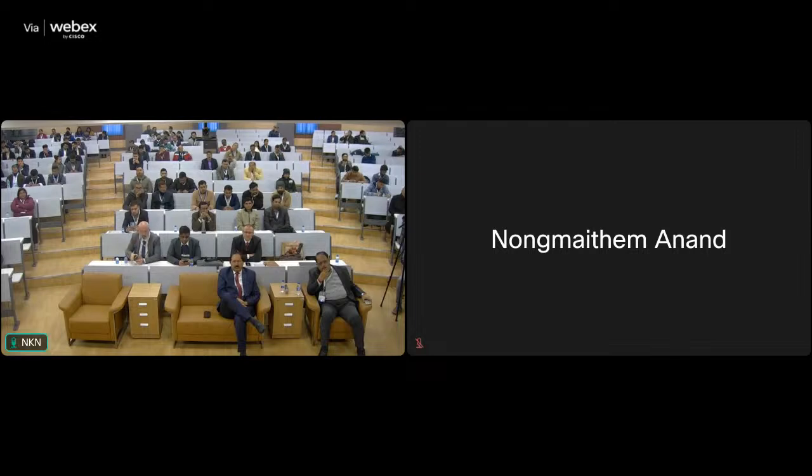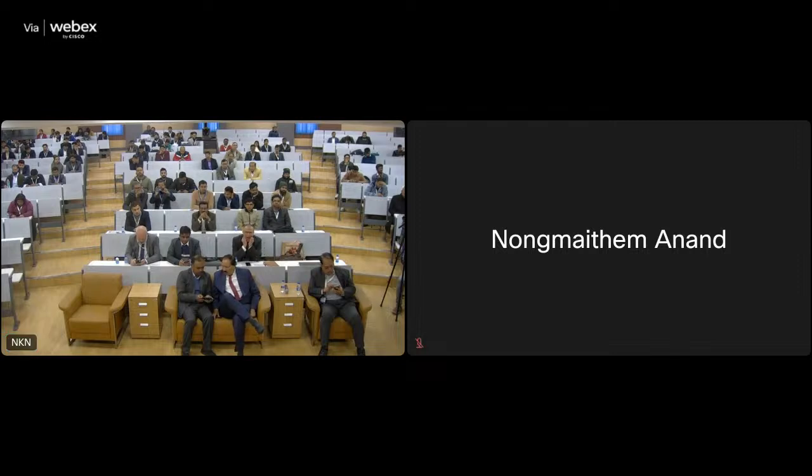Now, one example is shown here, and this is the Grimstad and Barton support chart. Now you see the blue dot corresponds to Q value 1, and I have considered a 10-meter diameter tunnel with ESR, excavation support ratio. Broadly, ESR reflects the factor of safety. The underground opening which requires more safety is given a lesser ESR value, and for temporary mine openings and other openings of smaller size, the ESR value is more. So on the y-axis here is the equivalent dimension, that is the height or the width of the opening divided by ESR.